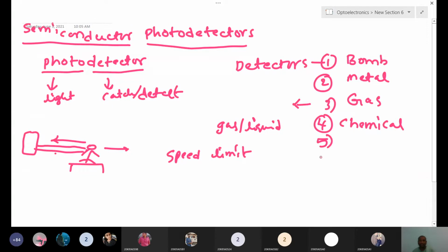Suppose you have a rail bridge and rail tracks. If there is a crack in the track, you can send sound rays or ultrasonic rays. They will find out where you observe cracks. If you send some waves here, there is a destruction of the wave, but at the same time on the other side of the track you collect the wave, but here you will not collect that beam.